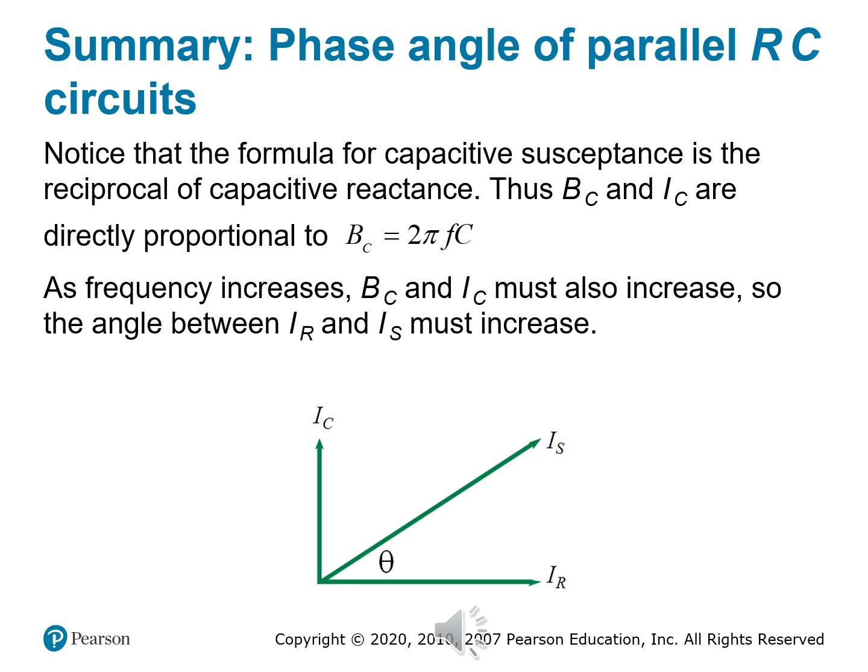Why did this matter then and why does it matter now? Because when you're doing AC analysis, the phase angle controls how signals add, cancel, or how they get filtered. Looking at this triangle, the relationship between I sub R, I sub C, and I sub S, this is your key or your tool to visualize how reactive power shifts with signal speed. It's also the backbone of frequency selective filters like tone control circuits or noise cancellation systems.